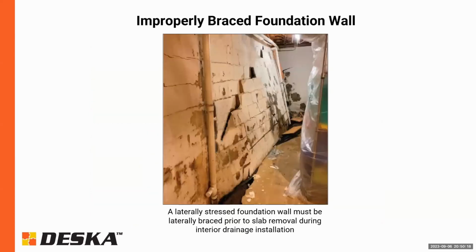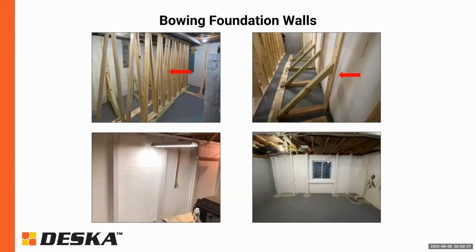Hey, Brian, is there a rusting concern where the beams touch the wall or in the ground there or anything? No, so the beams are all painted and then they're grouted as well. And it's in essentially a conditioned environment. There are clear cover requirements.